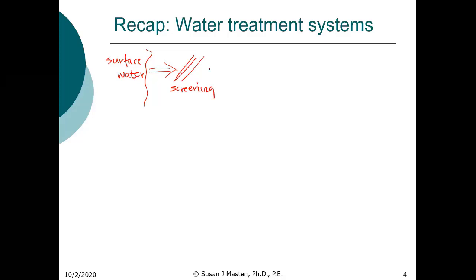From there, the water flows into what next unit up? So the next thing we would typically want to do, you do coagulate the sediments. Is coagulation. So the first thing we'll do is some sort of rapid mix. So we'll add our coagulant.